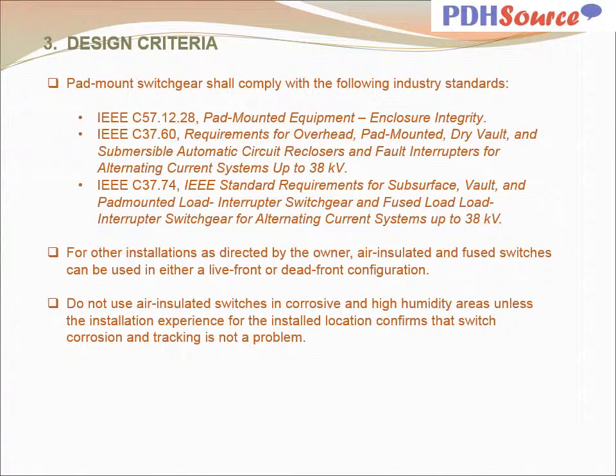For other installations as directed by the owner, air insulated and fused switches can be used in either a live front or dead front configuration. Do not use air insulated switches in corrosive and high humidity areas unless the installation experience for the installed location confirms that switch corrosion and tracking is not a problem.